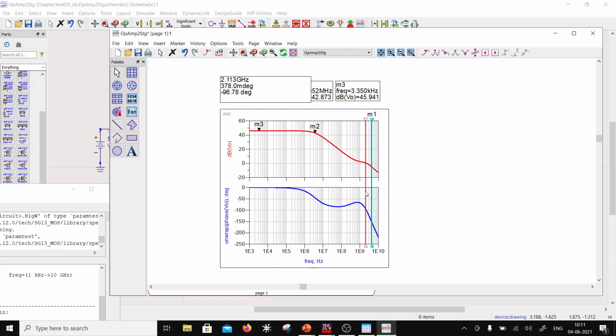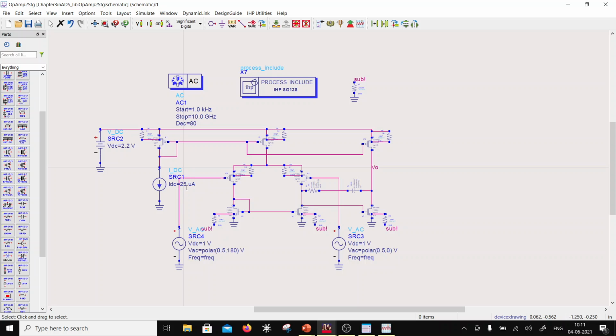So here I'm going to see the zero crossing. So this is M1. So the zero crossing is over here. So 102. So I have a 78 degrees margin here. The gain of the op-amp is almost 46, right? Okay, so by changing the length or by reducing the current, you should be able to do this, but for some reason it's not working. Okay, let's see. This should have common mode input. Common mode voltage range is very large, right? So this would not do anything, right?